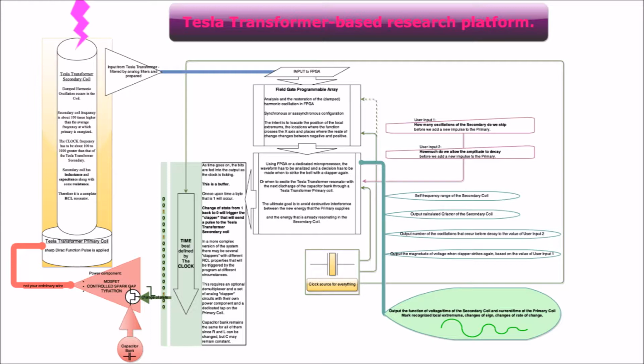This circuit, presented here as a block diagram, is a modified version of a phase locked loop system used in telecommunications to keep oscillations of a high-frequency oscillator synchronized with a resonator crystal, such as a quartz resonator or any other crystal-based oscillator.